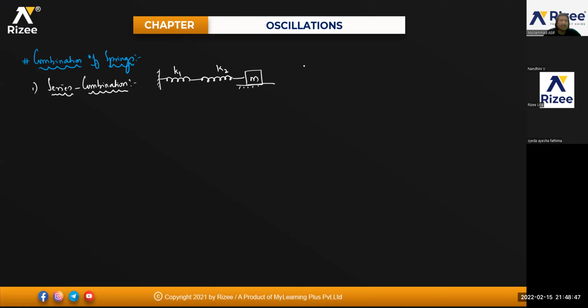When they are in series combination, I'll write 1 by K equivalent equals 1 by K1 plus 1 by K2. For two springs, I can write K equivalent equals K1 K2 divided by K1 plus K2.